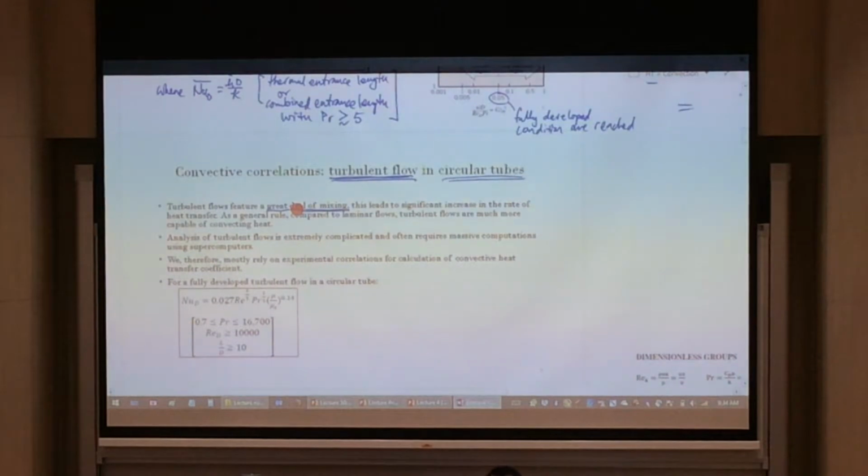So why would turbulent flow be a region of flow of interest to us? That's because in turbulent flow, you get quite a fair bit of heat transfer out or in. Why is that so? You could imagine if it's laminar flow, you still get heat transfer in or out. But if it's turbulent flow, there's a lot of mixing going on in there.